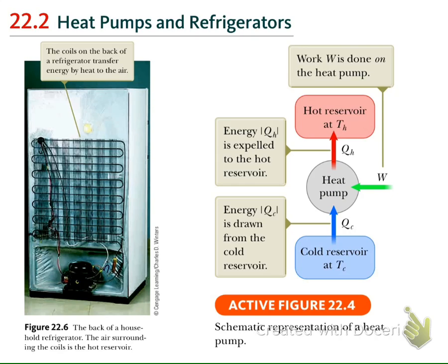An example of the heat pump is the refrigerator. The compressor is the one that does the job: you input energy to the motor in the compressor, and the compressor will pump the heat from the cold reservoir, which is inside the refrigerator and has the lower temperature, and put it to the hot reservoir, which is the environment outside the refrigerator.